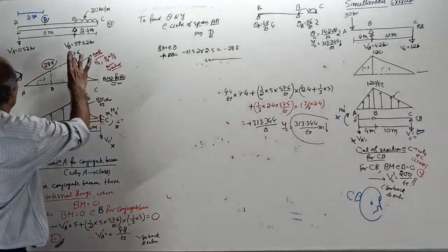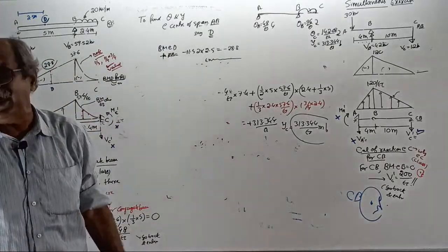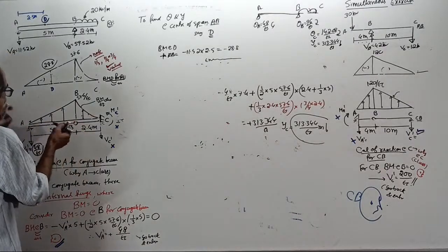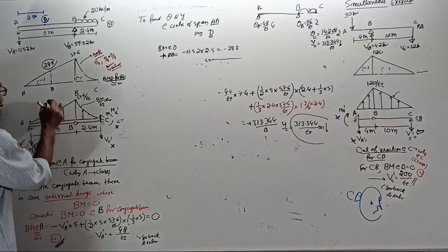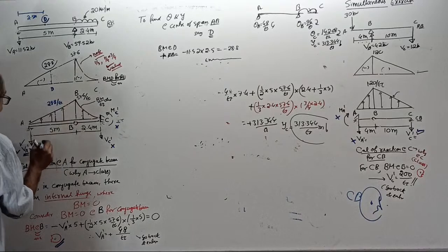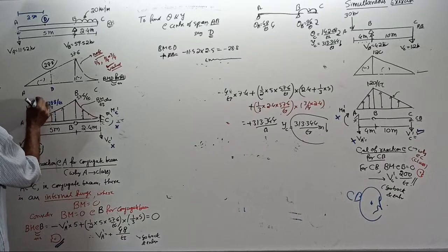If it is 57.6, this is half of that value. Directly you get it. Why do you want to calculate? Clear? You can directly see it there. Midpoint, half. Now, this value equals 28.8 by EI, and without disturbing, this distance is 2.5 meter. Don't disturb other things.